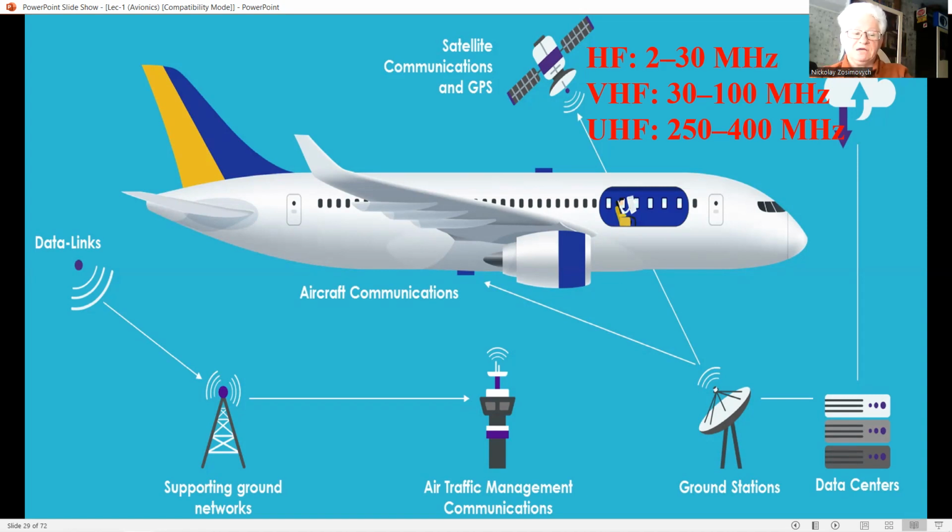Equipment is usually at duplex level of redundancy. The VHF radios are generally at triplex level on a modern airliner. Satellite communication, SATCOM, systems are also installed in many modern aircraft, and these are able to provide very reliable worldwide communication.